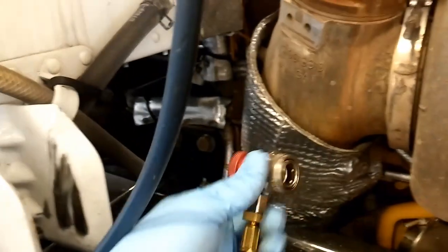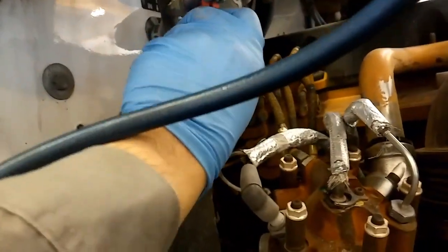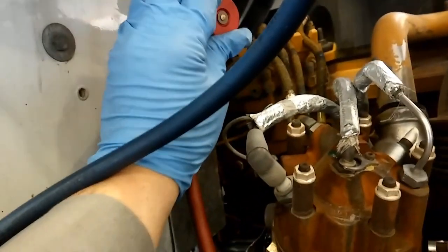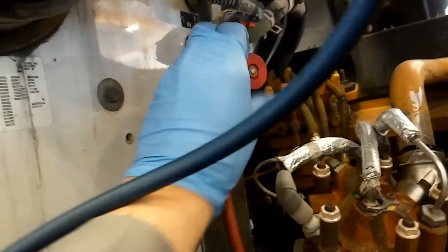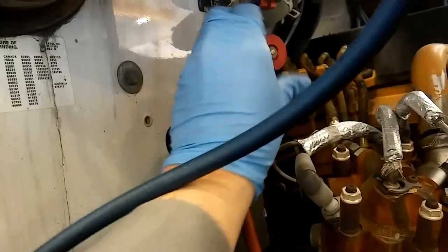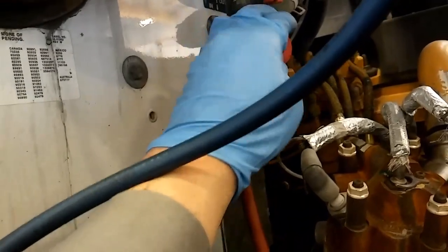Now here's where it gets tricky if you are trying to do this yourself and don't have an AC machine to recover the refrigerant. You're going to need at least a set of gauges and a vacuum pump to properly check this system and pull a vacuum on it after you've replaced any components. But what are you supposed to do about the refrigerant? If you don't have an AC machine, you can't really recover it. And it is illegal to just vent it to the atmosphere.